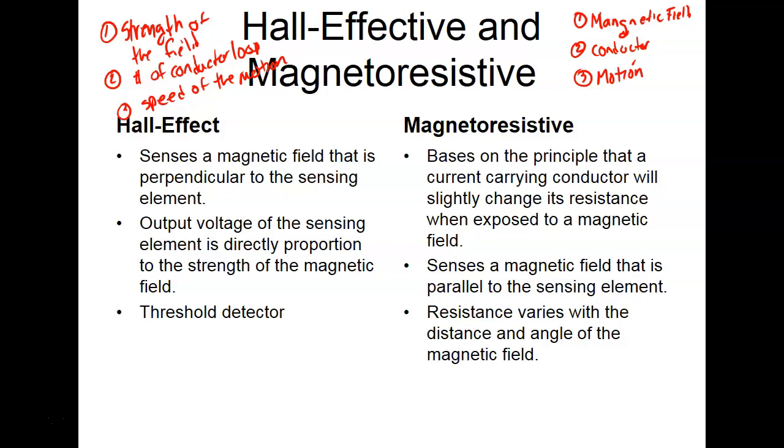So we have a meter that we call a clamp-on ammeter. Now, this is not an ammeter, it's a clamp-on ammeter. What this does is work with AC. Basically you've got the secondary of a transformer when you wrap that thing around the wire, and it's looking for the strength of the magnetic field. We don't change the conductors, we don't change the speed.